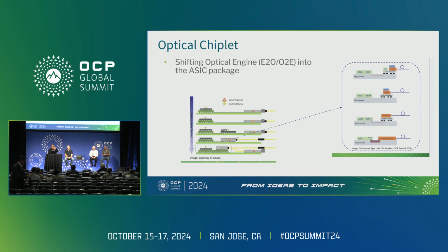Again, at the right side, you see different styles of being co-packaged. The optical engine could be single chip, could be multiple chip, and the connection could be over silicon interposer, advanced package, or even organic substrate package. For all these ideas, we were considering how we can enable Bunch of Wires to support die-to-die. Then we got to this kind of recommendation.